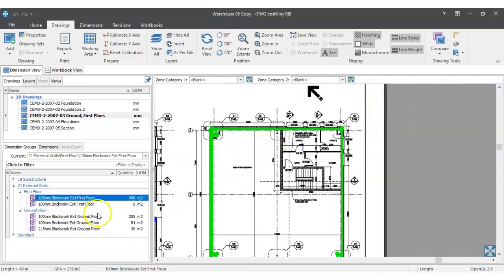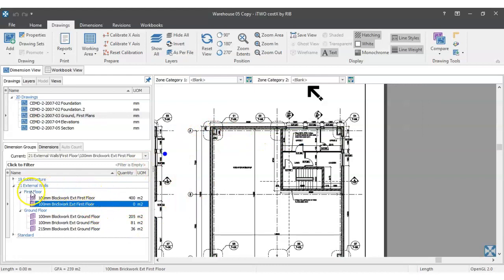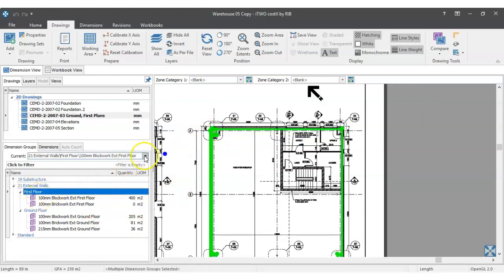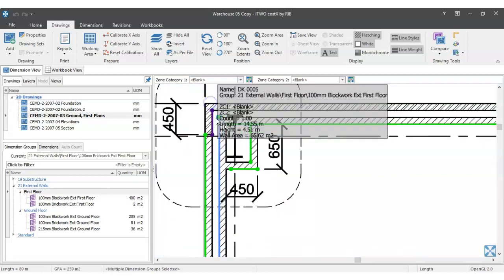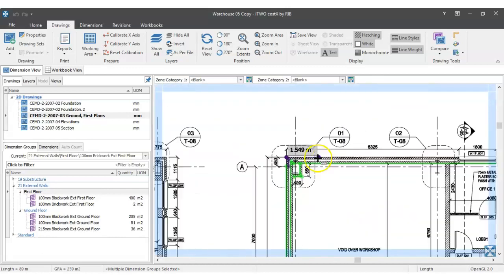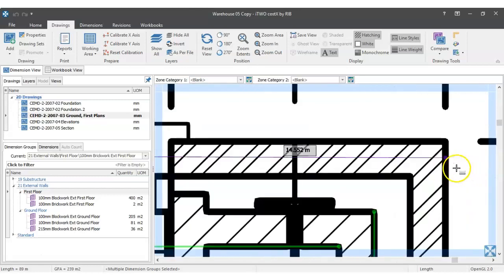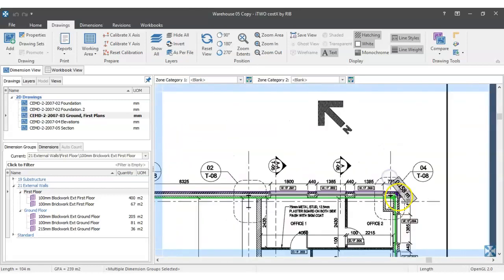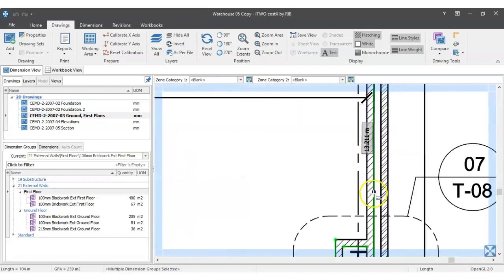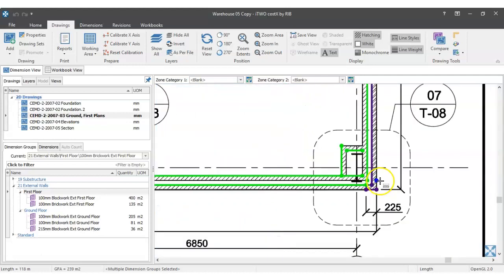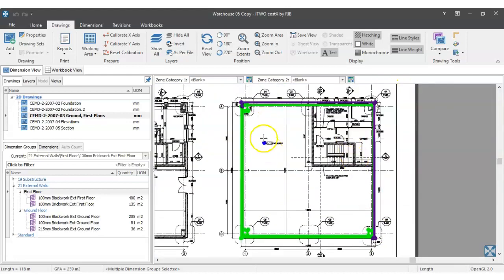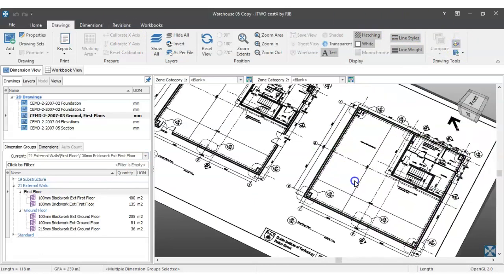I've just the brick facade to measure. And click that. In fact, what I might do is click first floor, use the filter here, drop down, click the brickwork so that I keep that block work open to see where I need to start off from. On the outside, all the way across to here, and this one I believe will go all the way down. I think I'm on the inside still. There we go, and then back to the outside, and that should cover all those external walls on the first floor. Let's take a look at the little 3D, just to see.